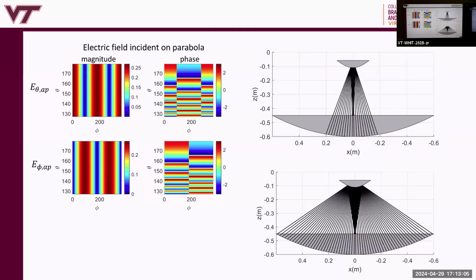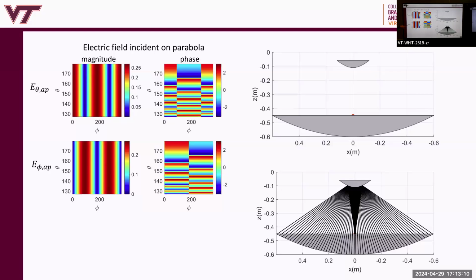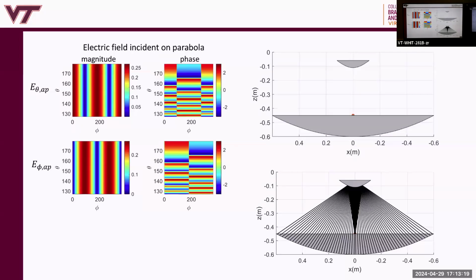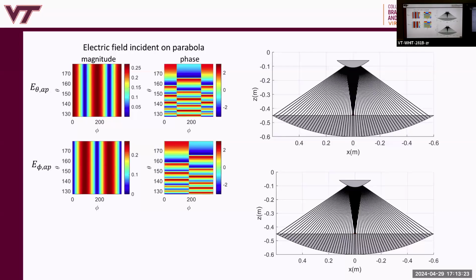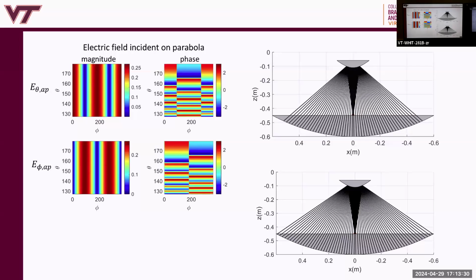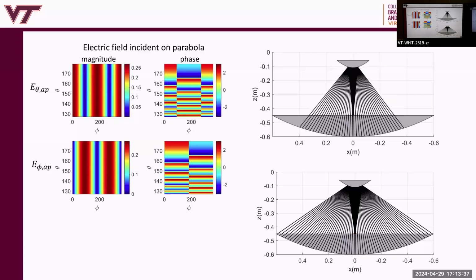But once you work out all those, this is the electric field theta and phi that you get in the aperture, and then you can easily do 2n cross Hi of that, right? And of course, there are standard ways, if you go to Balanis' book, to calculate the far field pattern due to that current density on that curved surface. You can use a Jacobian to project it back to a circular aperture, and then you just use the integrals in that circular projected aperture, right?